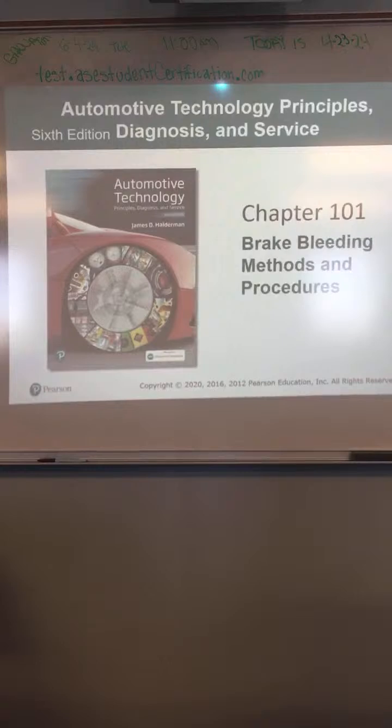The only time you have to bleed the brakes is if a part has to be replaced, a brake line, a caliper, a master cylinder, something where you open the system and have brake fluid leak. Under normal conditions, you should not have to bleed your brakes. If you're doing a flush and you do it right, it's not going to get air in the system, it's just going to change the fluid.